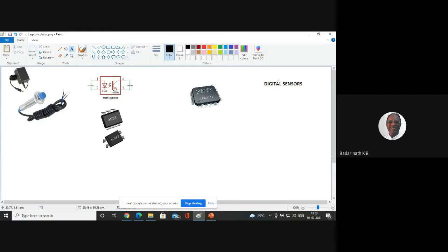For example, when do you use it? In the case of a CNC machine, computer numerical control, if the wheel is rotating, I want to know when the wheel has turned to a particular angle. If the wheel comes to a particular position, I have to initiate a certain action. That means I want just one signal, either on or off. Every circumference is 360 degrees, and whenever it reaches 180 degrees, I want one signal so that I can initiate another action in the machine. That's all I require.